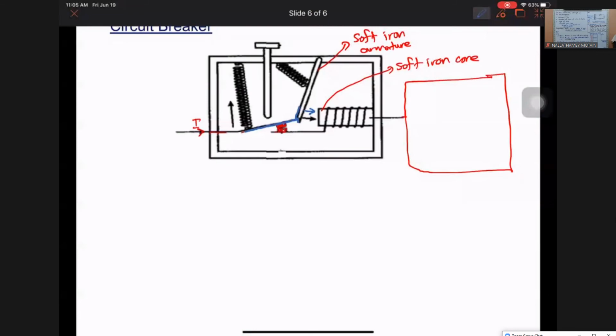When it's being pulled, let's say like this, it comes like this. Okay, pull, then the thin wire over here will move upward. I mean, it's no more in contact. Contact over here will be open. When contact open, no current flow. When no current flows, what happens? That means the electrical appliance is not functioning.